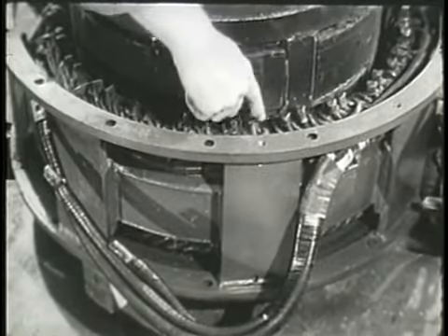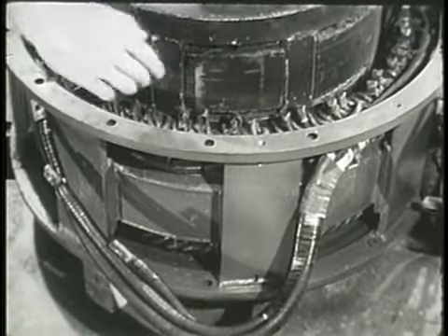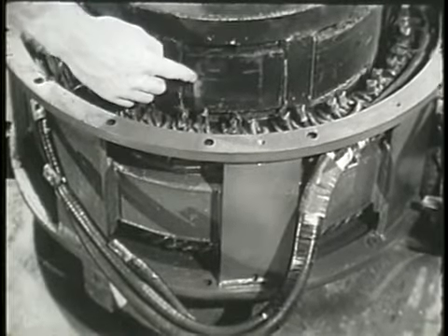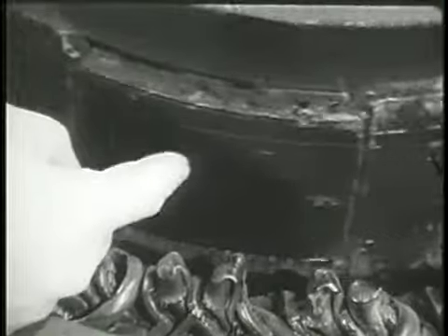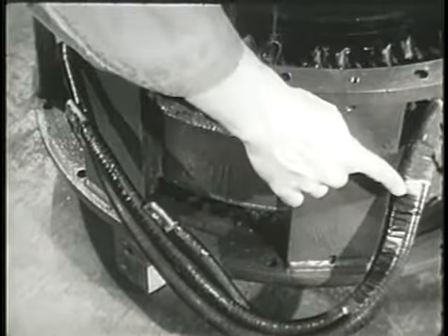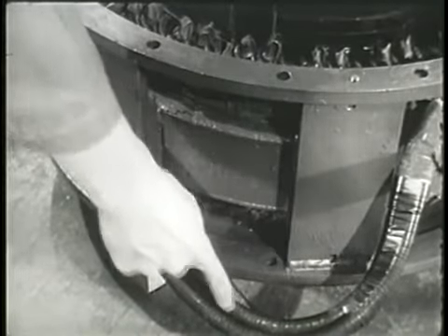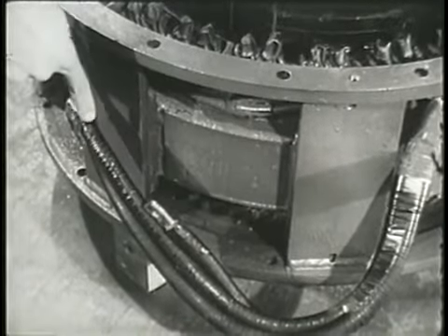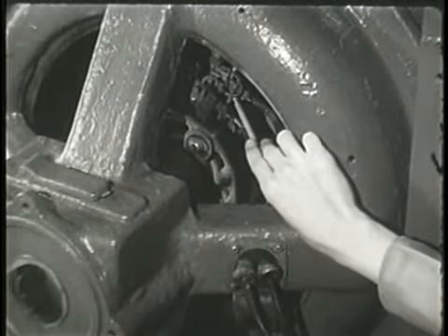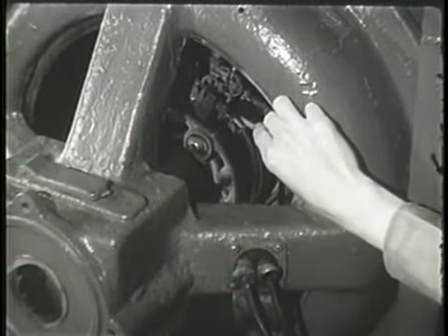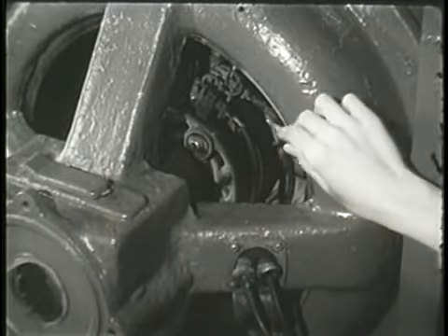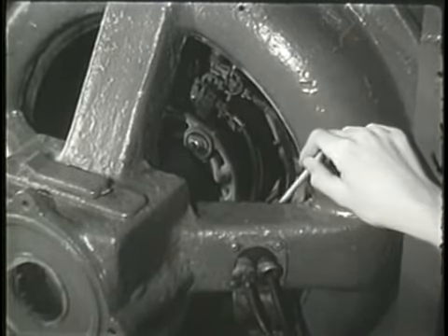Here, the coils of the armature are set around the circumference of the yoke. The poles of the field rotate within the armature to avoid the use of slip rings and to obtain direct connections to the load. Brushes and slip rings are used, however, to connect the AC generator to the outside low-voltage DC source needed to excite the field. Sparking brushes at low voltage does not represent a serious problem.